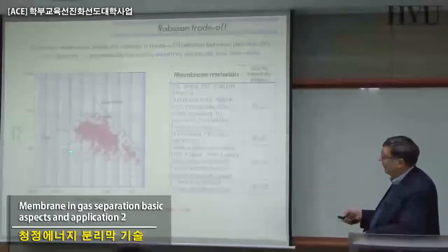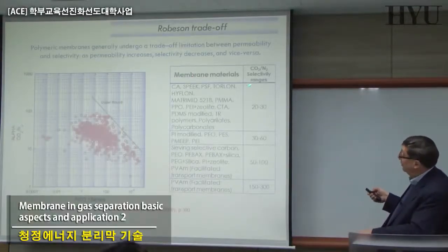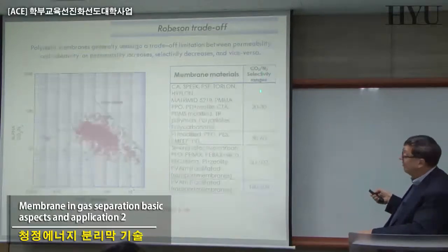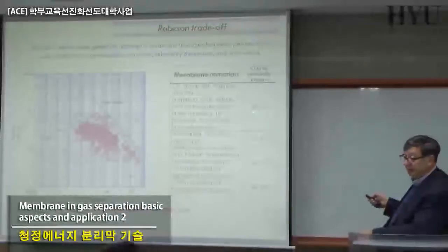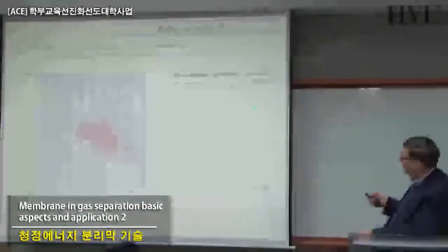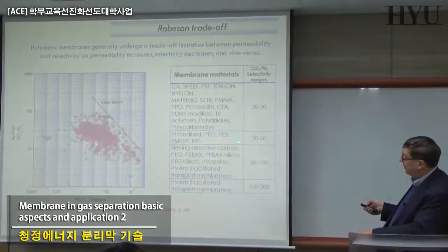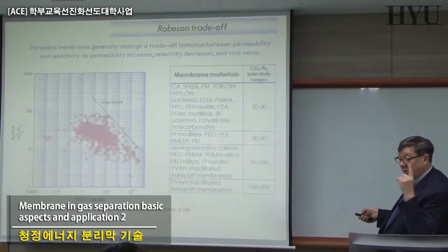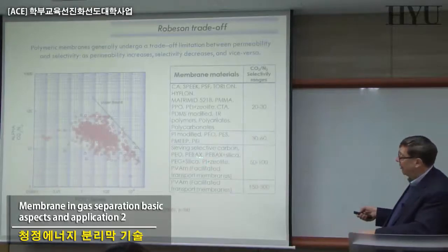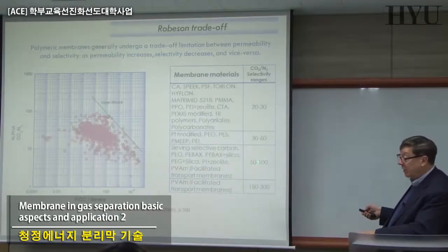And you remember this, so you know which kinds of materials are present. You can see here that the selectivity, as I was mentioning, for most of the traditional systems is too far from what we really need, 20, 30. If you go to some modified polyimide, etc., you can arrive at 30, 60. As soon as you start to have mixed matrix membranes, that we saw, PEBAX with silica or zeolite, etc., you can have something better.